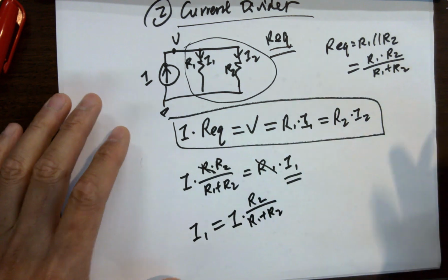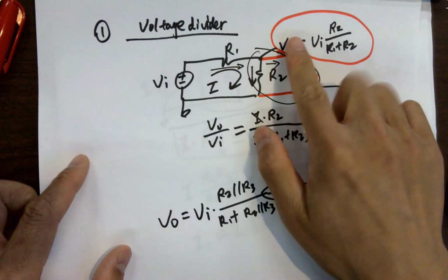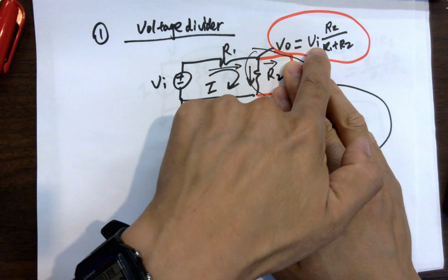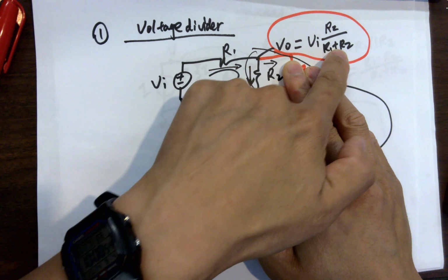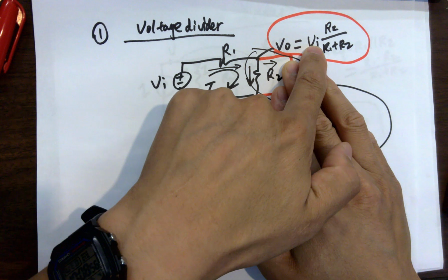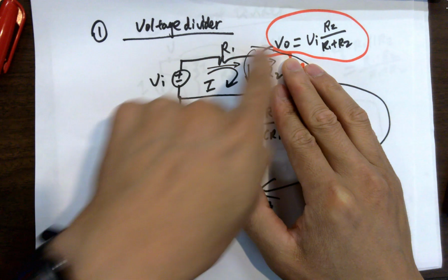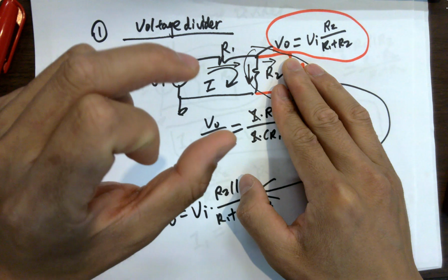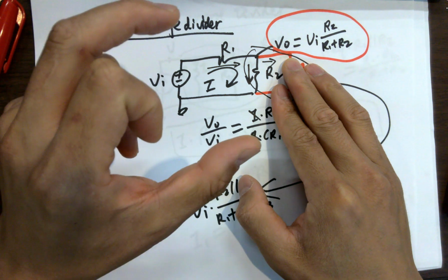I can find out, very interestingly, for voltage dividers, if you only have R2 here, right? Only R2 here. So the VL equals VI times R2 over the overall resistance. So that's the total voltage. So one quick method that you can memorize, or you can remember the conclusion here, which is: the resistance ratio equals the voltage ratio, if they have the same current.